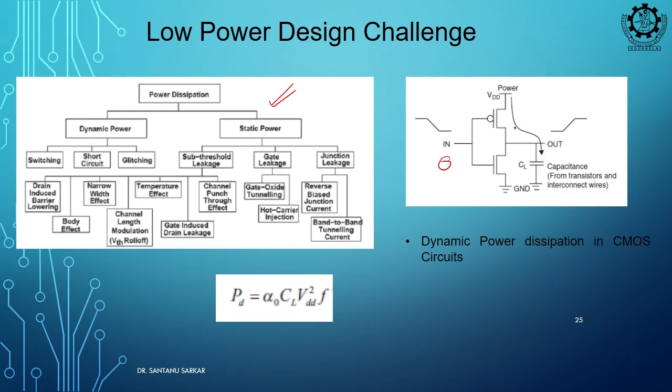Okay. Now, when we moved from BJT to MOS or CMOS technology, initially we were very happy. We thought that we had solved our problem. Why? Suppose your input is 0, input 0 means NMOS is off, right. VGS of the NMOS should be above Vt, then only it will turn on. So, NMOS is off, and the input is 0 means the PMOS source is at VDD, right. What is mod of VGS? VDD minus 0 is equal to VDD.